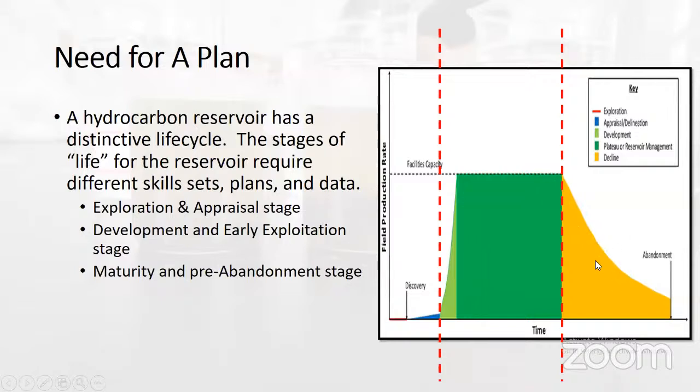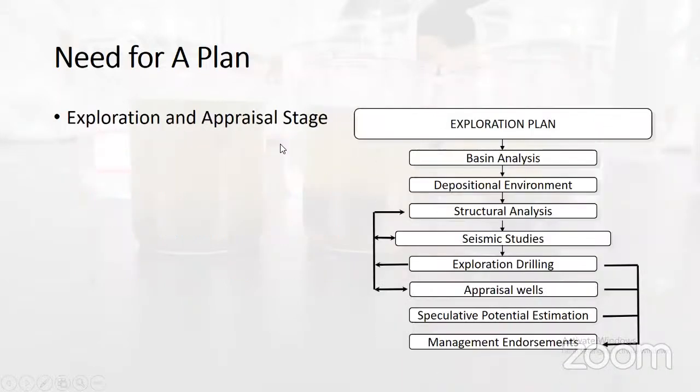At this stage, we can do some activities like EOR, we can use new technology, we can revisit the old wells to sidetrack them and so on, to maintain the production at the end life of the reservoir. At the middle stage, we can also study the possibility of applying water injection or gas injection and any secondary drive mechanisms.